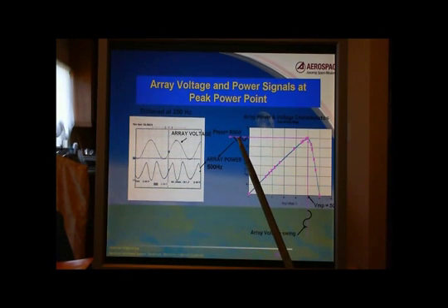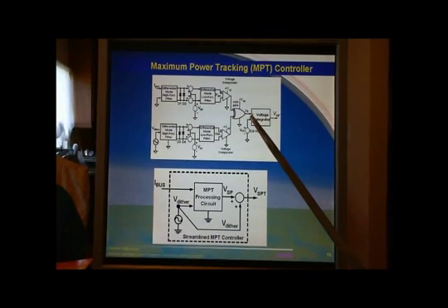The power ripple, or AC information superimposed on the power signal, has a frequency twice that of the solar array voltage ripple. In this manner, it is equivalent to an effective 90-degree phase shift of the power information. When this information is processed by the exclusive OR gate, it ends up with the same result shown in the previous chart, that V sub x will be 1/2 of the operating bias used for integration.